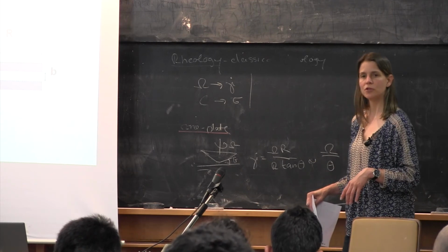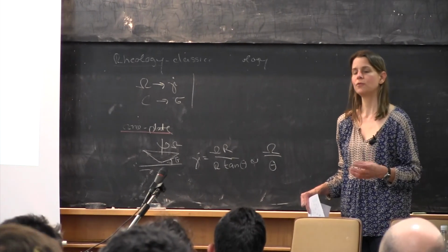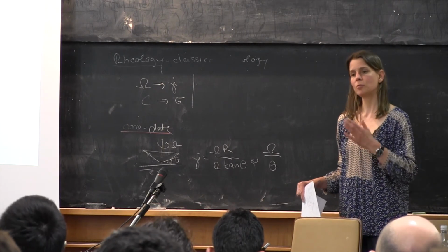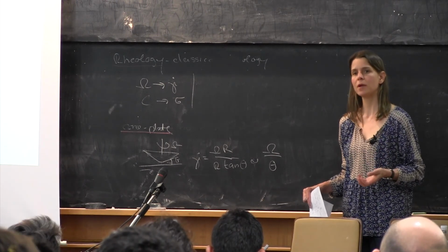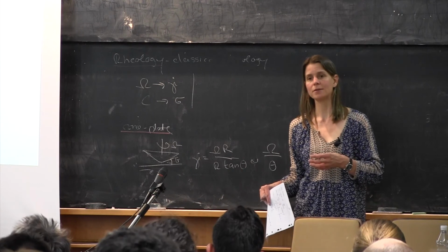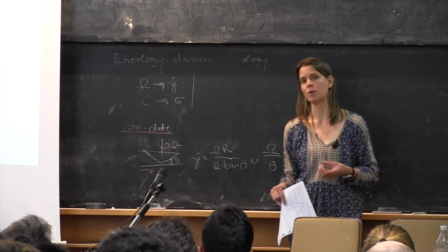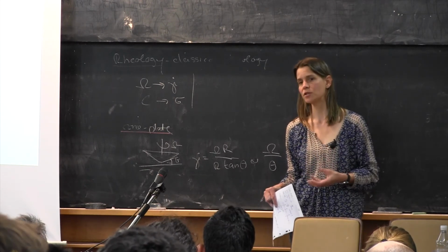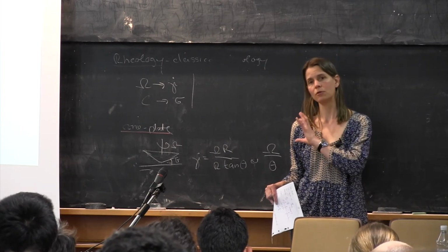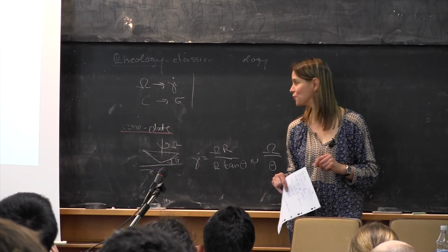what might be limiting about these geometries is that you're limited in the torque you can measure. So if you go to fluids that have a very small viscosity, or if you want to go to very small shear rates, you might be limited by the torque of the rheometer. So typically for rheological measurements of systems that are very close to the viscosity of water, or where you expect very small non-Newtonian effects, or if you want to look at small shear rates, the resolution of your apparatus will not be sufficient. And a lot of the suspension properties that we want to discuss in the following are exactly placed in this range. So the conventional rheometers are not always the best rheometers. And that's why we'll talk a bit more about microfluidic rheometers tomorrow.